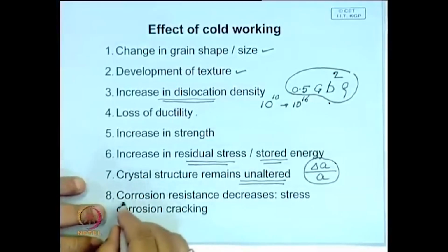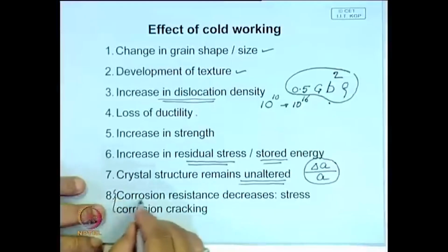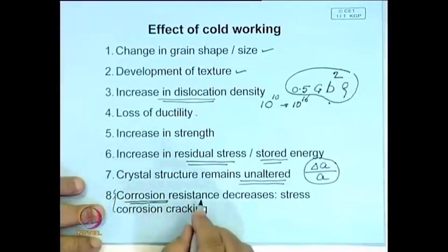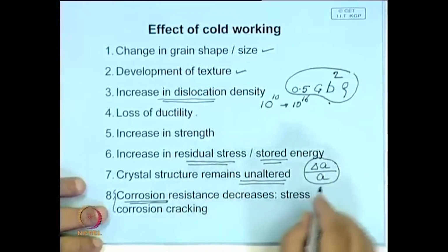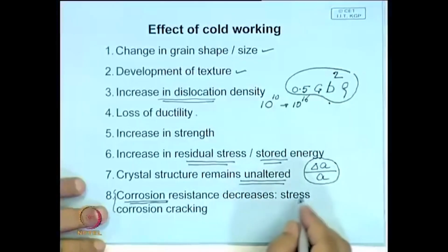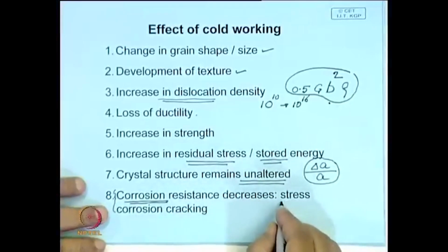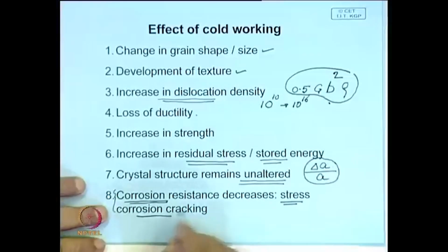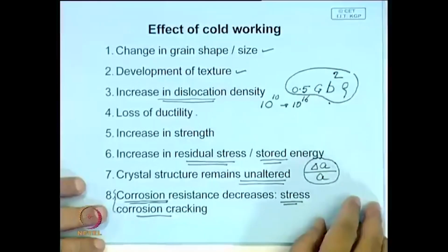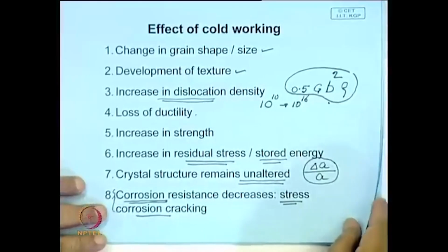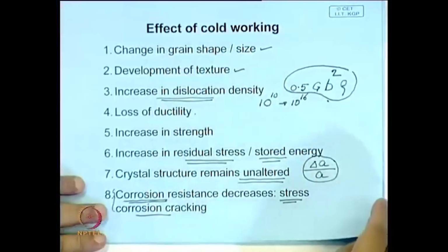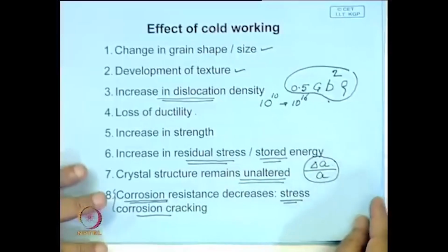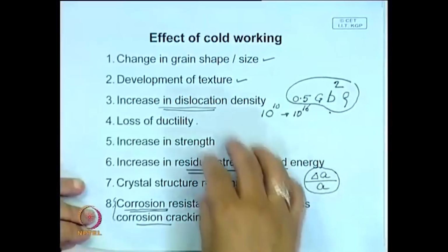And cold work material is in a relatively unstable state. Therefore, its reactivity with the environment may increase. So, the corrosion resistance of cold work material usually decreases, and in some materials, because of the presence of residual stress, they are susceptible to stress corrosion cracking. Therefore, sometimes the cold work material may not be used in the cold work condition, and it will be given a treatment called annealing treatment, which we will know about a little later.